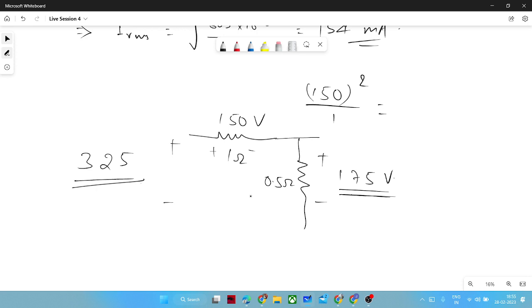Go ahead, Sanjay. If we had to calculate the effective voltage at the output for a full wave rectifier with a capacitor filter, in a similar case where the resistance is there, how would you compute that? Because the capacitor would charge to a different voltage now, right? And the ripple voltage would be different.